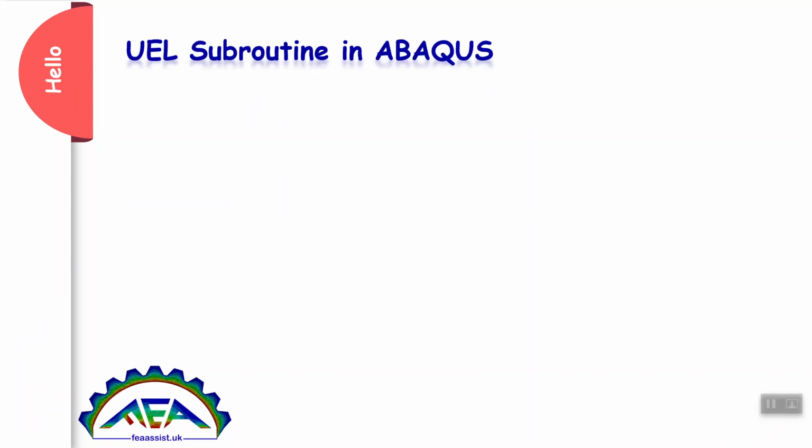Hello. You want to learn UEL subroutine in Abaqus easily and quickly. UEL is a subroutine to define a new element in Abaqus. Consider you have a one-dimensional element with points A and B. For example, temperature in this element is interpolated between the temperature of point A and the temperature of point B. So an interpolation function computes and defines the temperature at any point in this element.